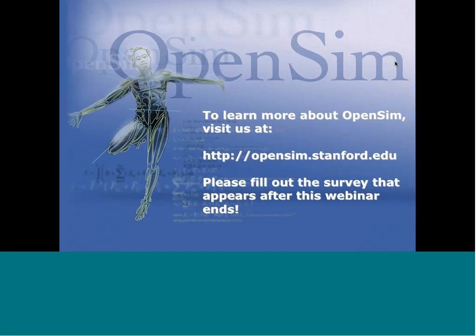You can disable the muscles, but if you want to remove one completely, it has to be done outside the GUI. You could do it by editing the XML file, and if you're working with the model in Matlab scripting, you could do it there as well, right, AJ? You could. Yeah, you have to remove it from the actual set that it belongs to, so from the force set.